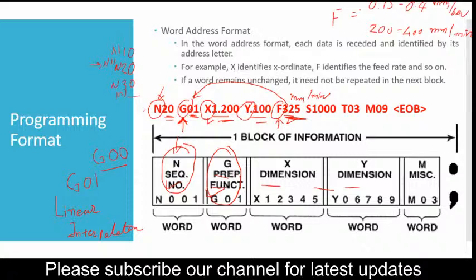If it is a turning center or CNC lathe, I should write feed rate in mm per revolution. And if it is a vertical machining center, that is a milling center, then I should give the feed rate in millimeter per minute. It is a linear feed and a rotary feed. In order to actuate this, we will be using certain specific G functions that we will be seeing. So feed rate can be in two senses. Here, if it is 325, obviously it must be in mm per minute.